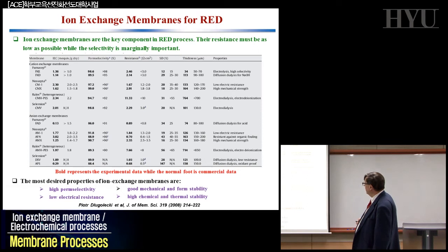They are resistant against organic fouling. There's a lot of interest today also in this kind of system to utilize not only fresh water, but organic solutions, where you have to extract or remove salts, or to utilize it for reverse electrodialysis. So membranes of this kind are under investigation, and what you have to try to realize is high perm selectivity, high transport numbers, and low ohmic electrical resistance.